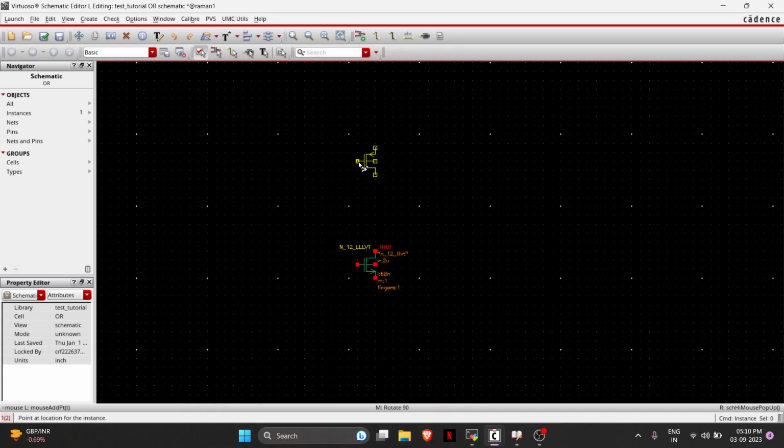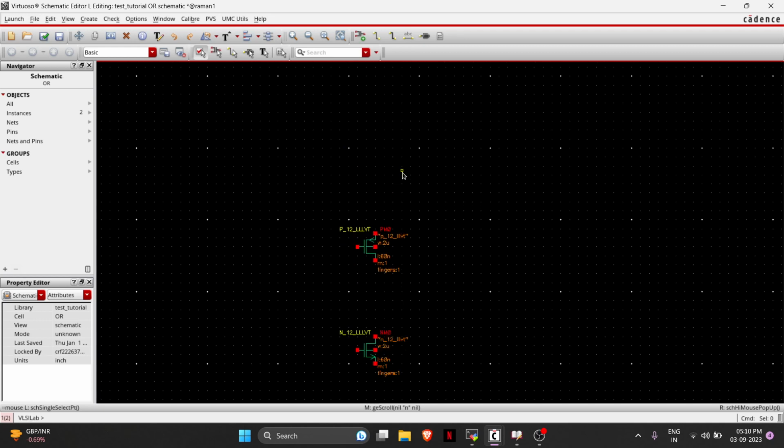We have our PMOS. Now we will be making this gate in our CMOS configuration. So this is what it looks like. So we need OR gates. So copy this one and place it here. And better we first set the widths.